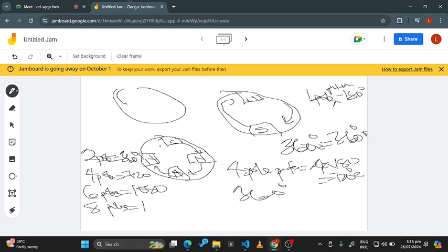So I have two poles giving me 360, four poles giving me 720. Then we have this relation: the total electrical degrees is equal to the total number of poles divided by two, which is capital P over 2, times 360, the total mechanical degrees.